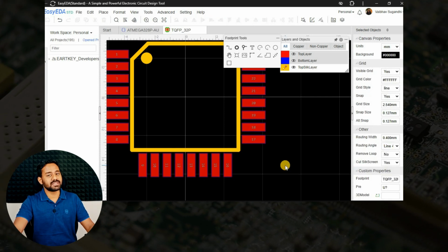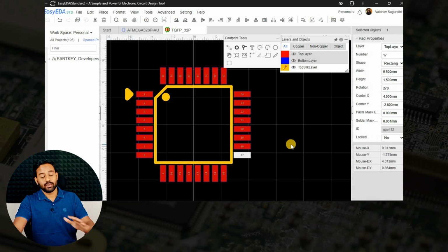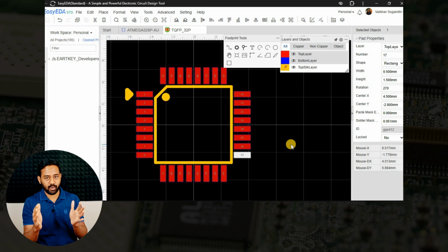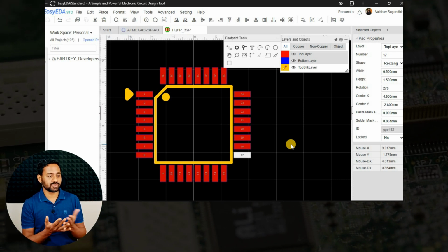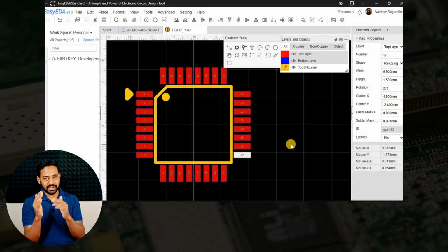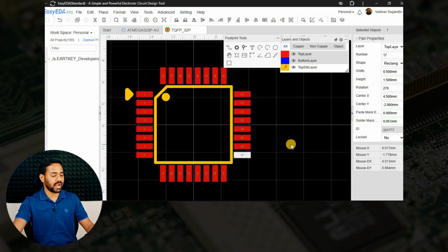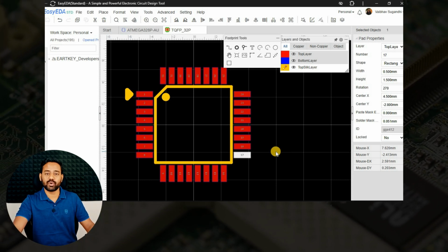So right now I'm considering professional manufacturing and I have given the pad width as 1.5 mm. You can go up to 2 mm and reduce the inner border which we have drawn with the top silk layer using the yellow color border line. You can reduce it a little bit inside and make it even a little smaller and go with the 2 mm pad width. But right now I'm good with 1.5 mm.